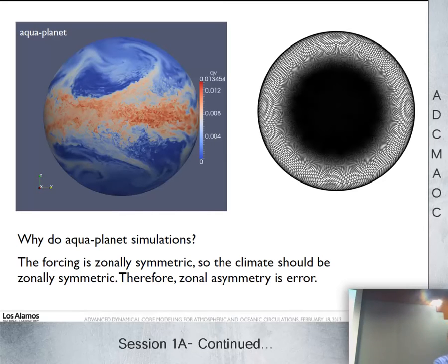No. So we're using a low-order finite volume method, and so absolutely, if you were throwing a fifth-order discontinuous Galerkin method at this, you could have very coarse, very rough, unsmooth meshes, and I think still get a nice result. But for us to get quality results, we need smooth meshes. We actually haven't tested yet how fast this mesh transition can be. I'll show you some pretty aggressive meshes tomorrow. I think we're okay there.